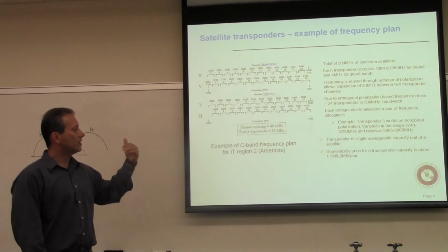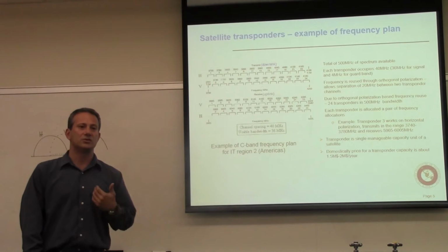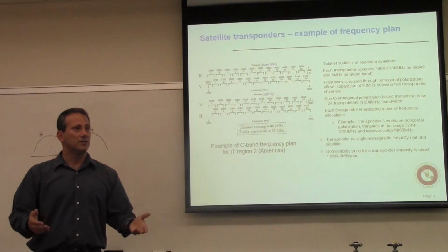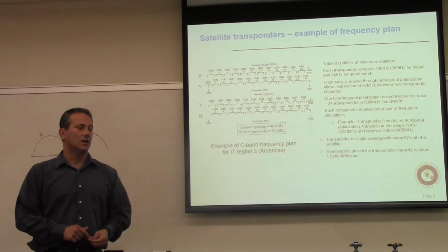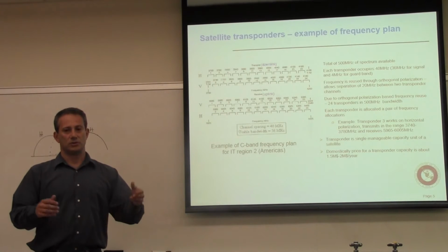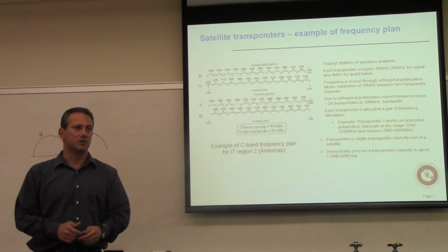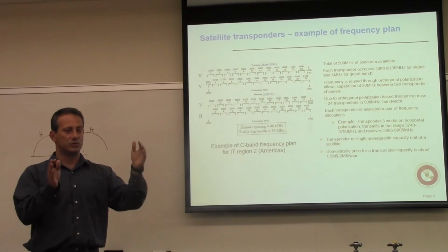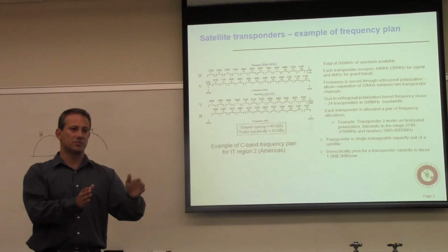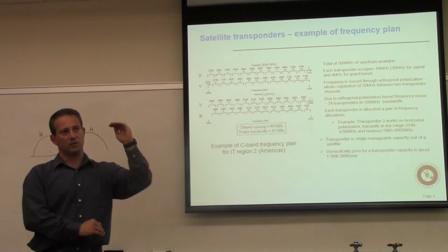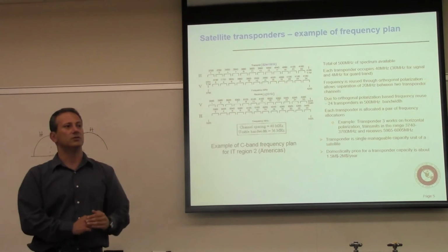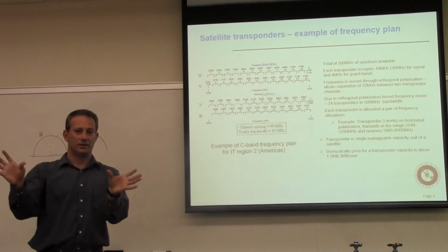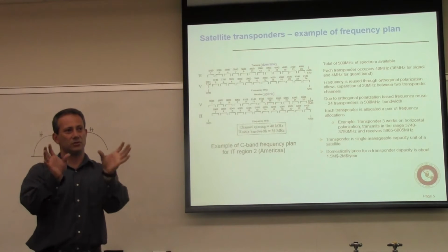And then as a satellite provider, what is it that you sell? You sell transponders, right? You sell transponder time and the transponder band. Typically you sell entire transponders, but there are some cases where you can get a portion of it, and you say you use this much of the transponder frequency band, but then your limits on the link budget need to be really strict, because you end up having signals coming from different places that you need to mix, right?